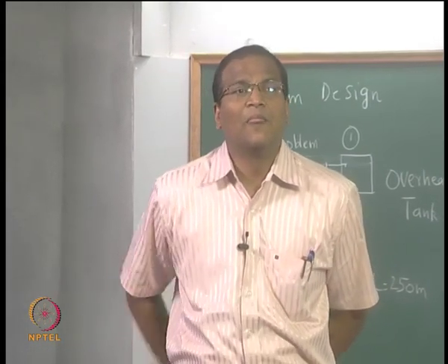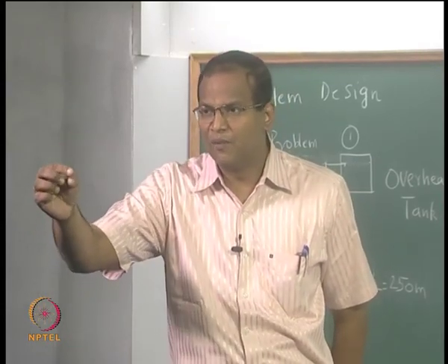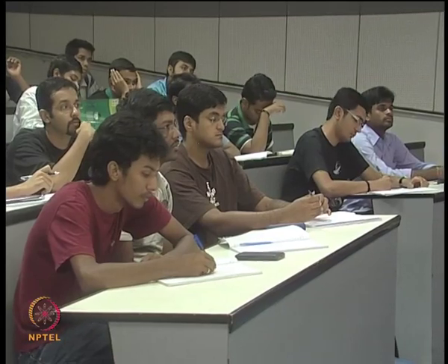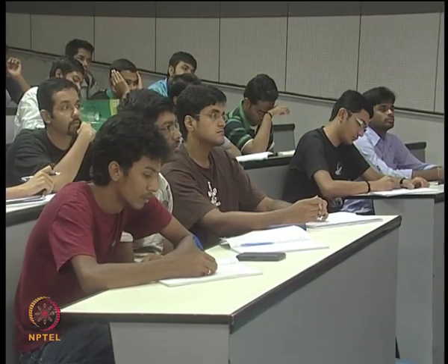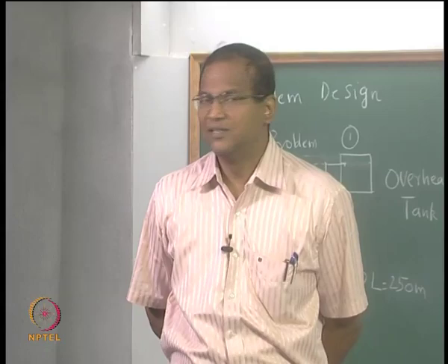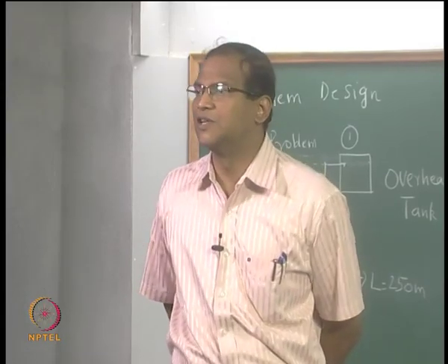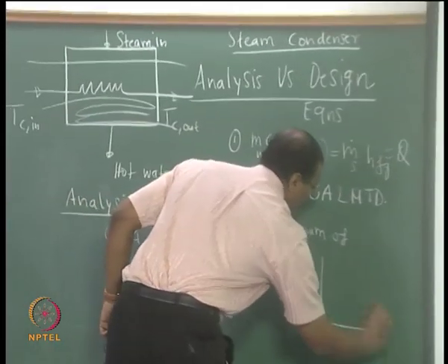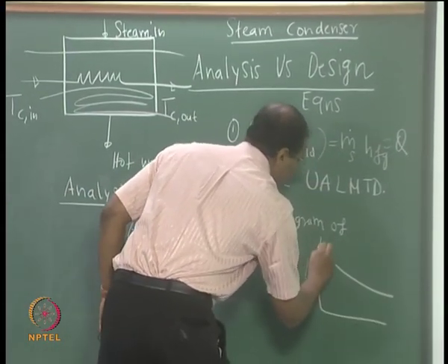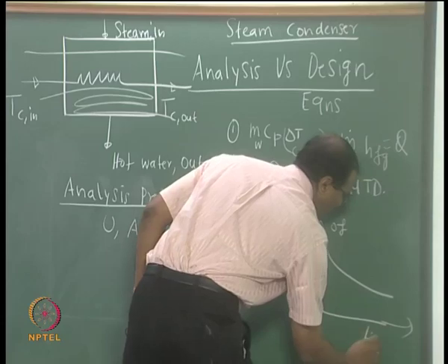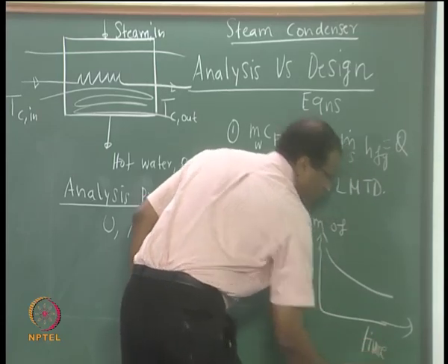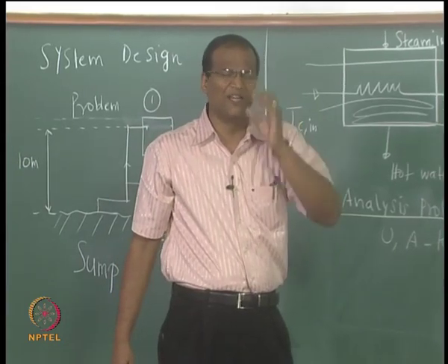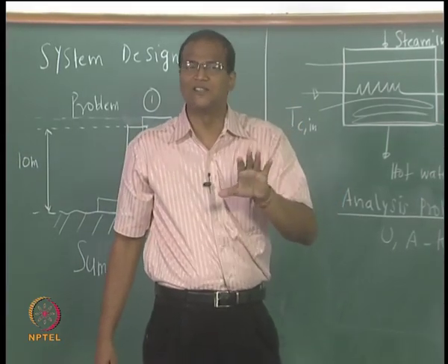Scaling, which is called fouling. Because of that there will be a build up of biological matter and all these things, because of which the resistance to the heat transfer increases. The resistance to the heat transfer increases, the heat transfer coefficient will exponentially decay with time. Therefore you may have a situation where you will have an H which is going like this. So design of heat exchangers or heat transfer equipment for life is not such a straightforward task.